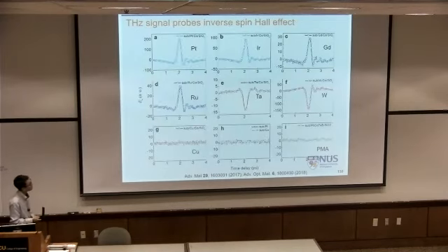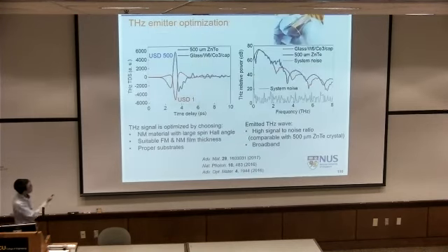He spent enormous time on materials, understanding interfacial optimization. Then he found 6 nanometer tungsten, 3 nanometer cobalt on top of glass. The substrate is very important, not to absorb terahertz, so it can give a very high power emission. And we compared with the commercialized zinc telluride crystal. This is a quite expensive gem, half millimeter thick. You can see the power output is almost the same as our thin film 9 nanometer, sputter prepared device.